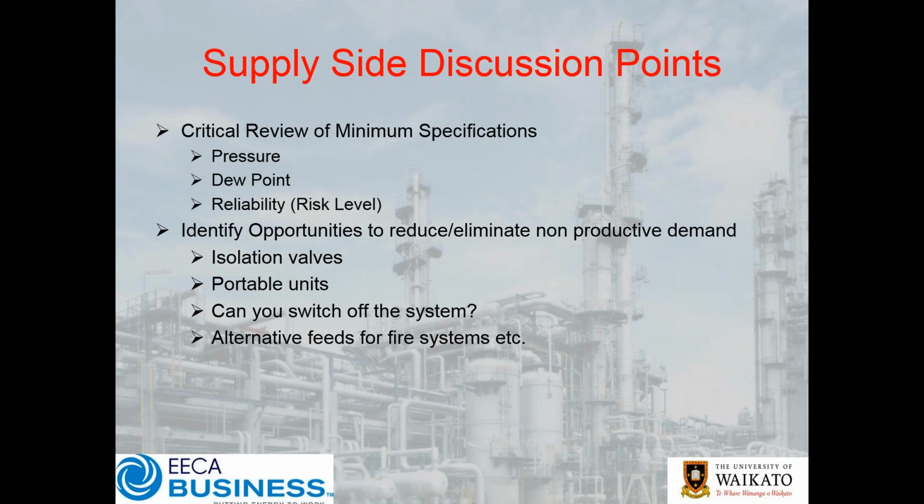Sure. So yeah, I'll be happy to have this conversation with you offline. We can talk about it in more detail. But effectively, you do need to be mindful, and this is important while we talk about getting your critical review of your minimum specifications. So get to understand what your desired point is as opposed to what your absolute minimum fail-safe point is, and so you want your set point to be, in a dew point case, below that, so that you've got some headroom, and so you need to then control that accordingly, and depending on the nature of the type of dryer, you need to get that right.